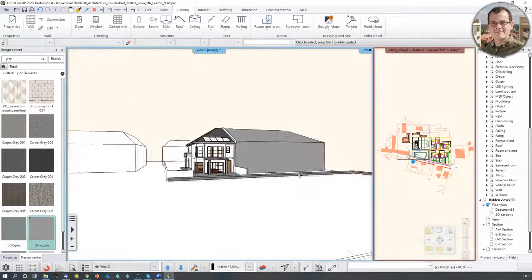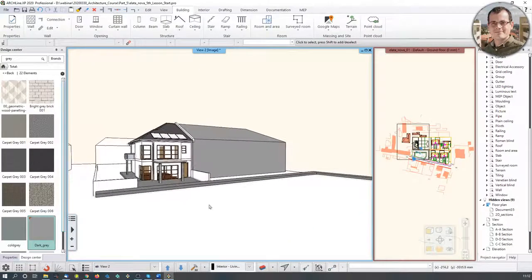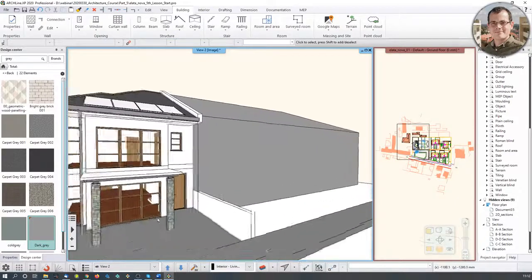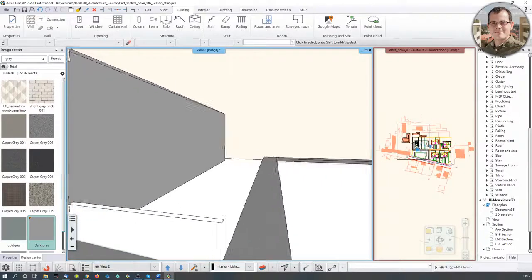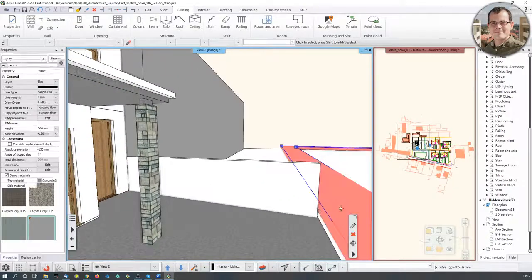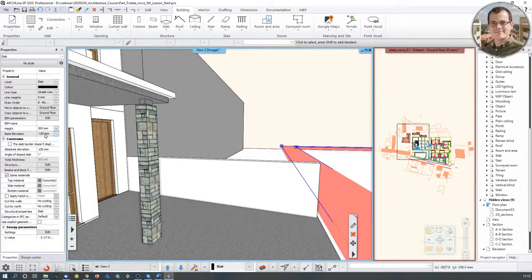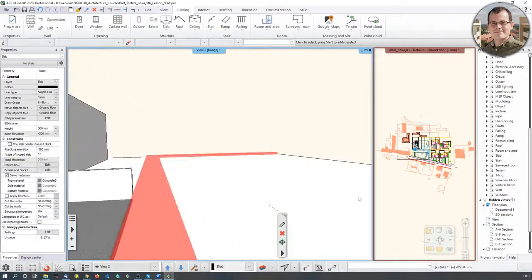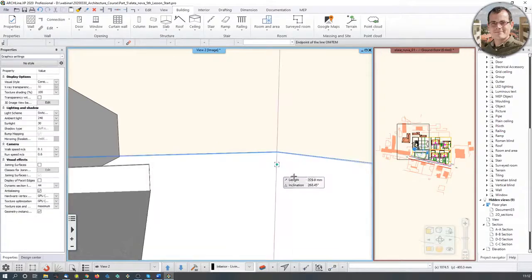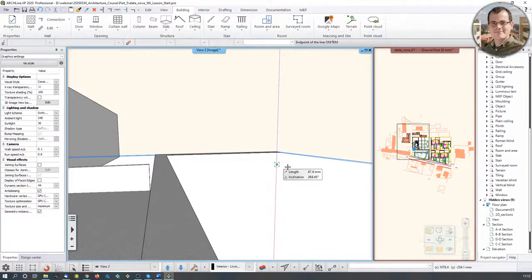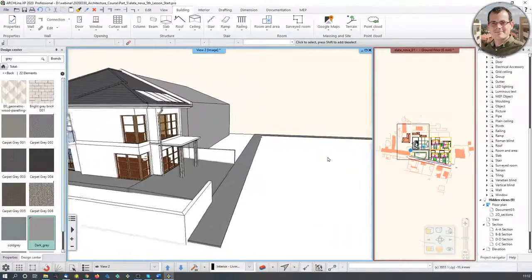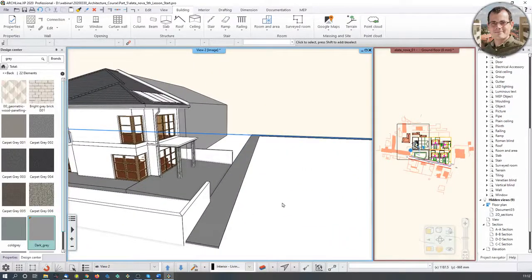And now I see I have a big piece of sidewalk, which I think is even too thick for my purposes, and it's actually floating around in the air. Now, this is the time when you can use the offset, so just select the element and change the offset to something else, maybe minus 300, or if you're at the very early conceptual stage, just select the item and find its marker and just move it downwards a bit, and then you would be ending up with the right outcome. Okay, so now I have a sidewalk, but I need to signify the street, which is an asphalt covering.